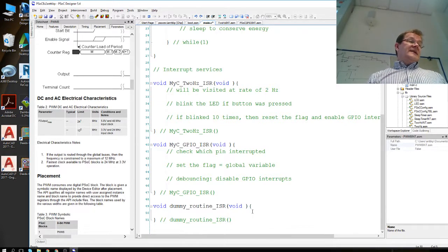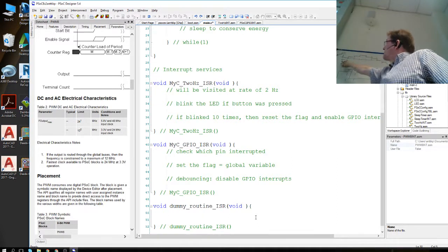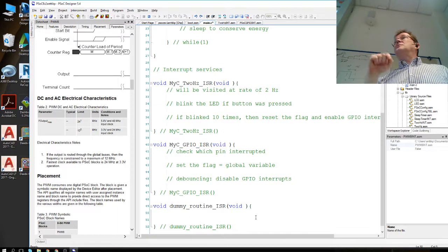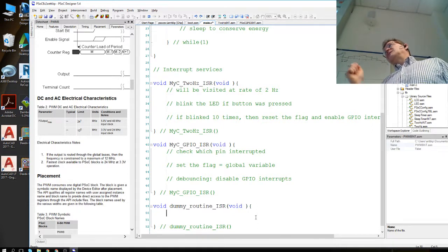Inside of that one, you would use a loop counter because you want to wait for 100 interrupts before you do anything. You can use a global variable, but you can also use static local variables. So a static local you can initialize at 0, and after that you can use it and change the value.